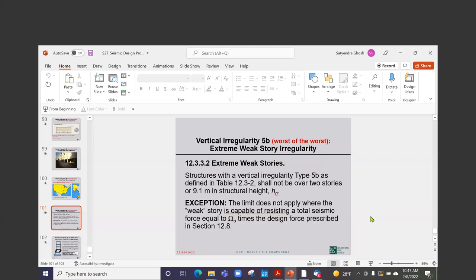So look at that part of BNBC, serviceability load combinations, which we do not have in our codes, and go with that. But again, in the vast majority of cases it doesn't make any difference, because gravity does not cause drift, unless, and this is a big unless, it is a very unsymmetric building. Then gravity will play a role.